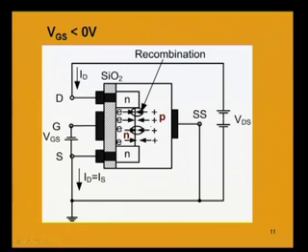Ultimately, this whole channel will be depleted of any single electron. That means there will be no electron existing in the channel to take part in the conduction of current. The channel will be totally depleted of the free charge carriers, electrons. So, the current will diminish to 0.